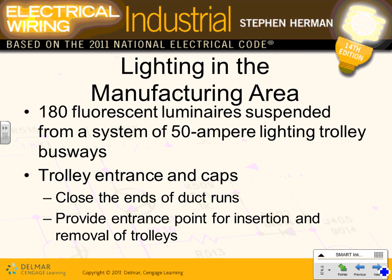To buy bigger, yes, it's more expensive, but it solved the problem with your voltage drop in this case too, because now you have a panel and you put that panel where the load is located, right in the middle of it. Okay, lighting. Here's what they did in lighting.